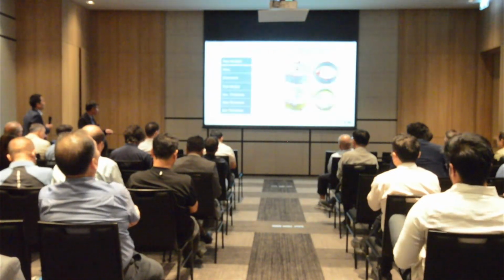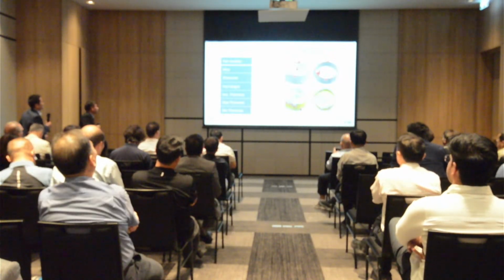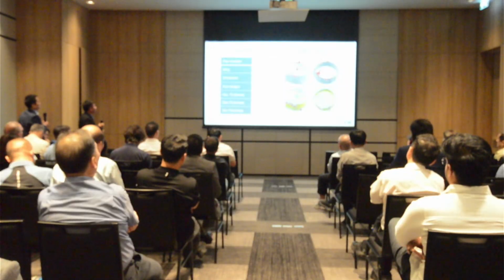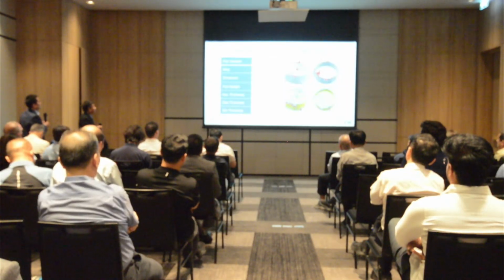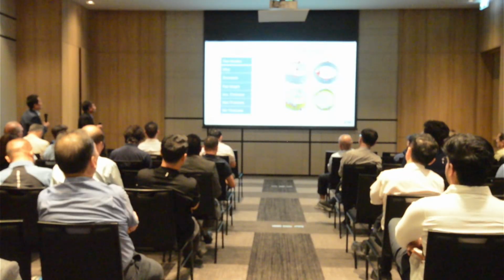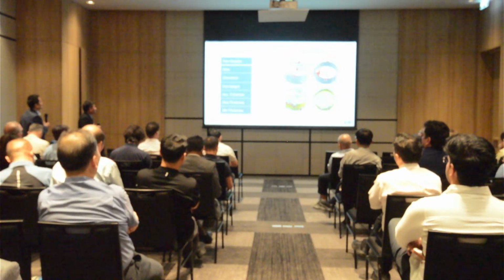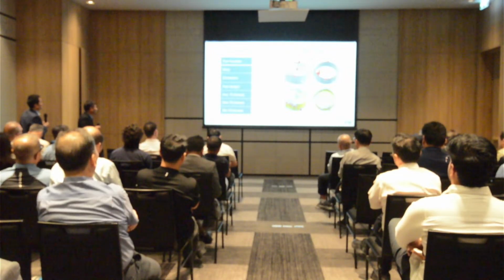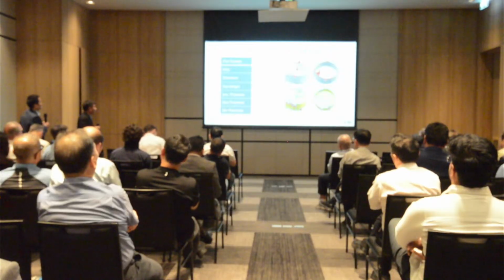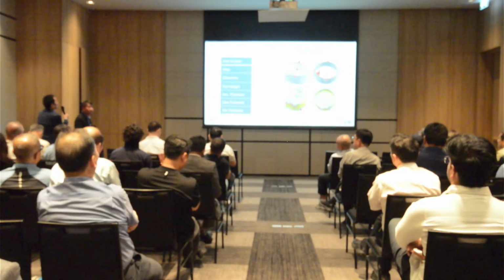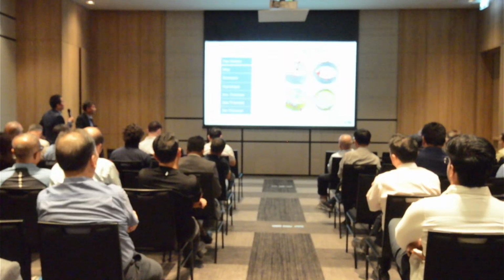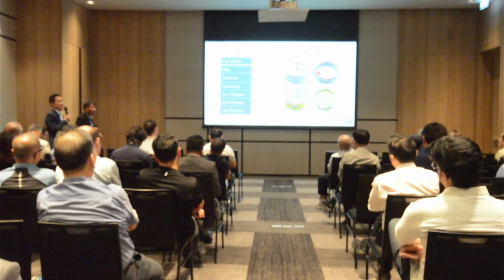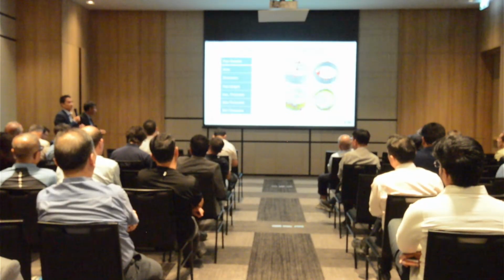Next page. Next, I will give an example. This is a case study. The part name is a housing. The alloy is ADC 12, the dimension is 251 by 204 by 123, and the part weight is about 1.5 kilograms, 1575 grams. The average thickness is 4.75, the thickest place at the hot spot is 13.72, and the thinnest place is 1.29 millimeters. This is a very typical part, and the range between minimum and maximum thickness is big. This is very challenging for liquid die casting.